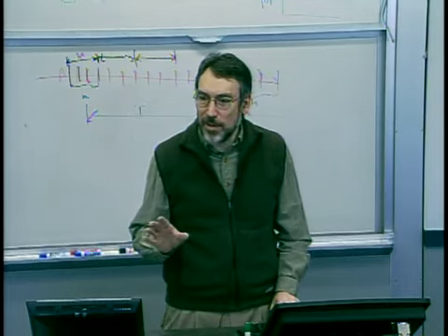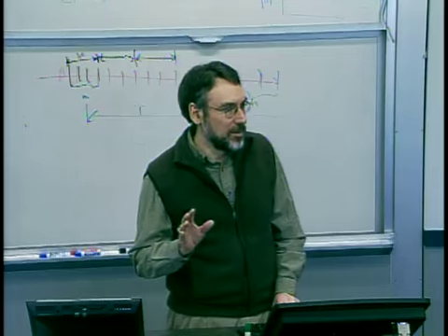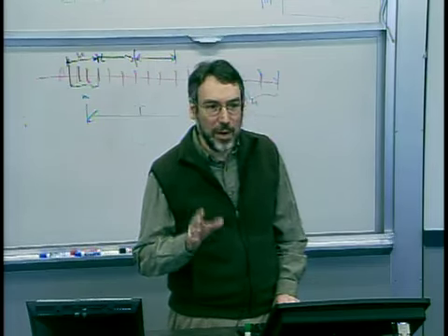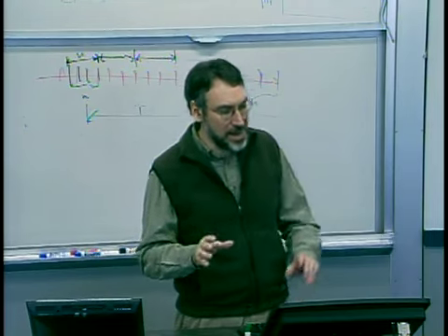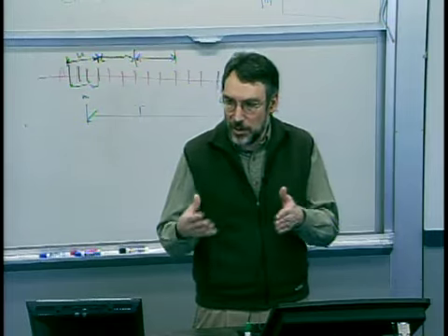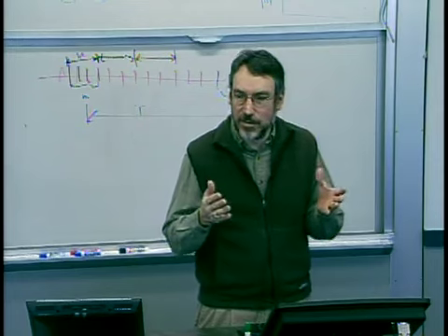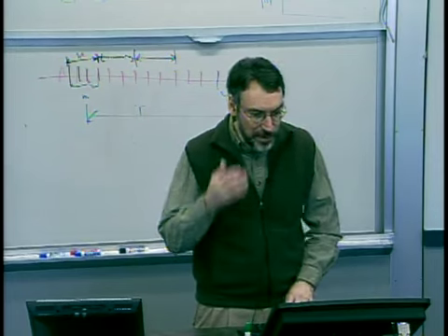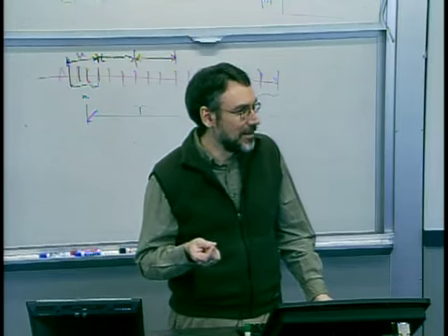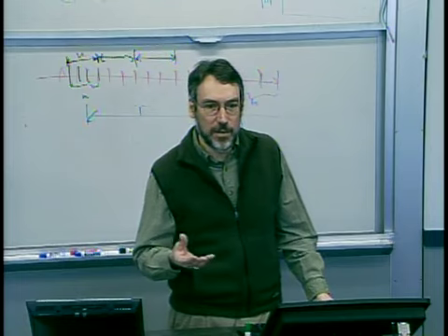Now, the idea of a quality loss function is a beautiful idea that actually conforms a little bit better to what we really care about. One can think of a quality loss function as a penalty function for any deviation away from our target x star. Okay? Now, graphically, a typical quality loss function that is used is a quadratic cost for these deviations, okay?